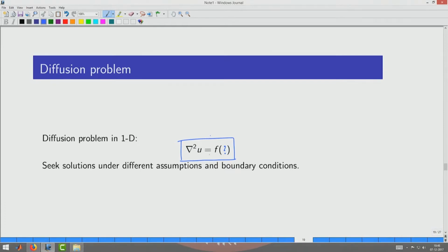So, if you just pay attention to this, let us say on the right hand side you have got 0, which means that the velocity variation would be like a straight line. And here, if RHS is 0, you get a straight line; if RHS is constant, you would have a quadratic; and you would have a cubic polynomial if RHS is a function of only, let us say, x2, and so on. You could have sinusoidal functions, exponential functions, and so on, as the case may be.